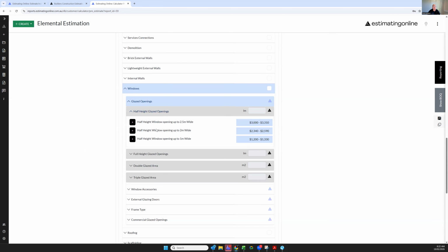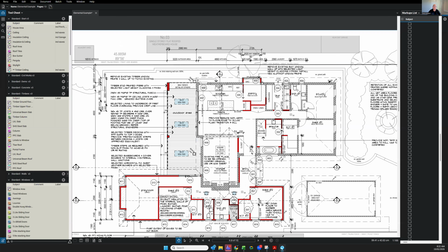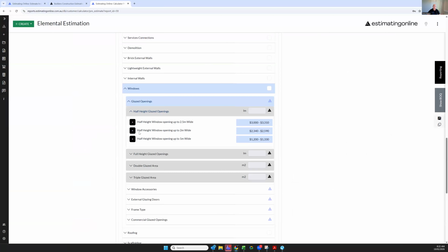And then I have my half height openings. If I just go, there are 1, 2, 3, 4, 5, 6, 7, 8, 9, 10, 11, 12 meters of half height opening windows multiplied by 1.5. That's going to get us square meters. And we should be pretty close to what it would be if we did it the long way.